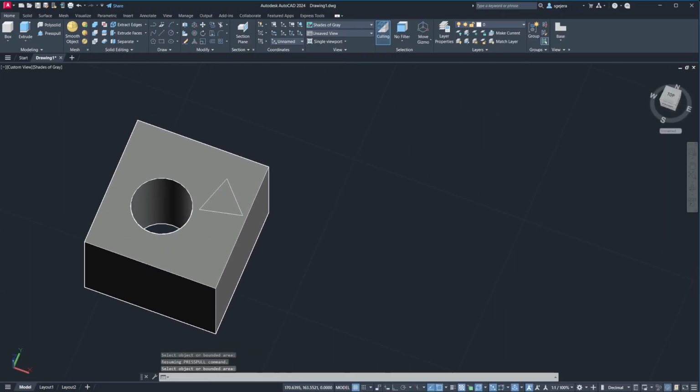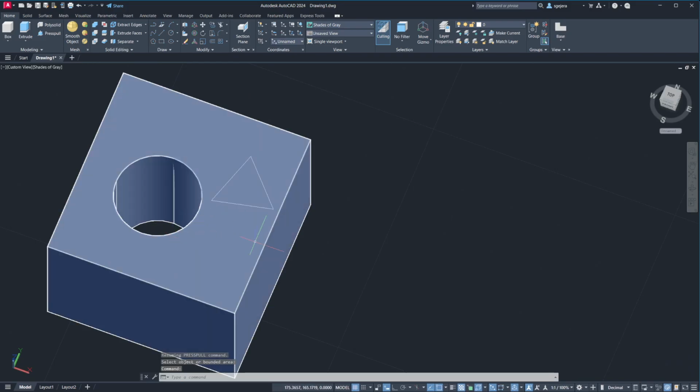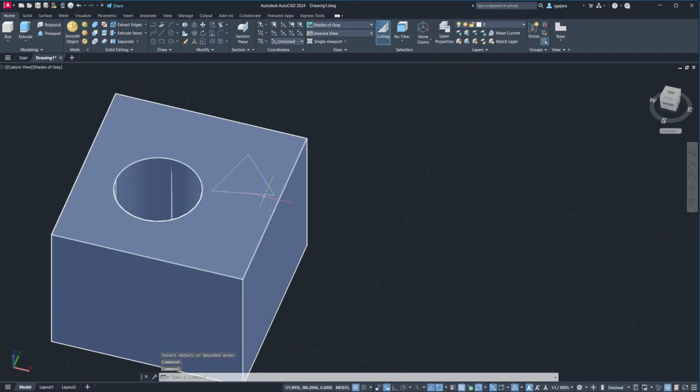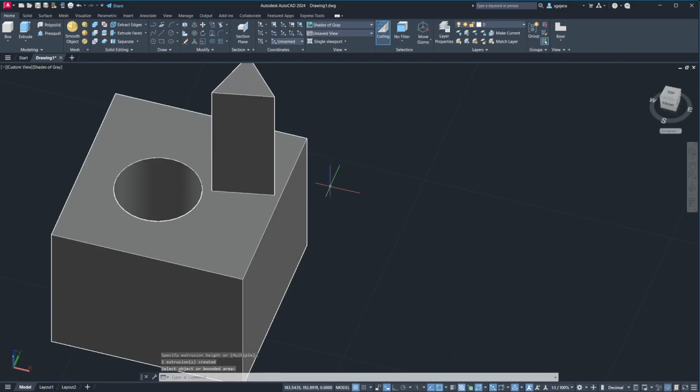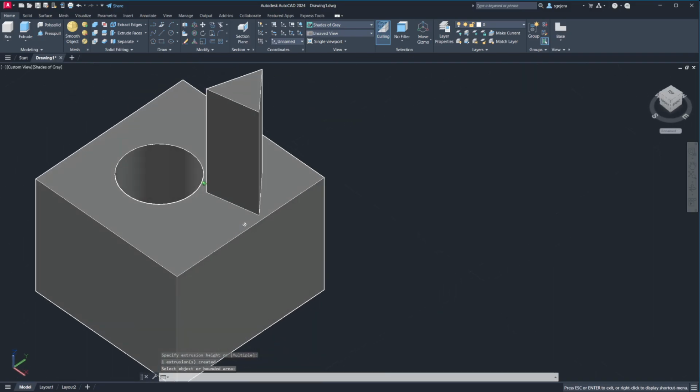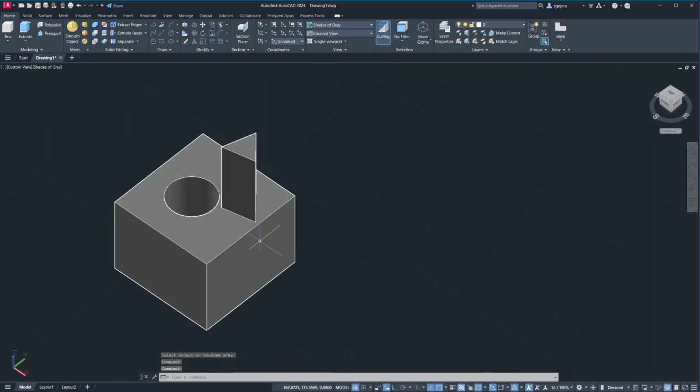So that's press pull. You can press it down, but you can also pull it up. For example, if I do press pull and I want to pull it so that this triangular prism becomes a protrusion on this box, I can pull it upwards like so. And I'll have something that looks like this. That's why it's called press pull, because you can either press it downwards or pull it upwards toward a particular shape. Okay?